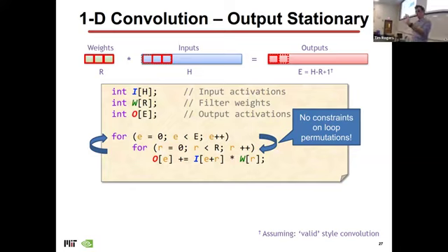It makes the loops simpler when we're thinking about how we map the outputs, the inputs, and the weights to these DNN accelerators. So for the rest of the code examples, we're just doing 1D convolution. There's basically only an X, there's no Y, so you only have to go across one bound. You can hopefully extrapolate this to 2 dimensions, but it's way less code to show on the screen.